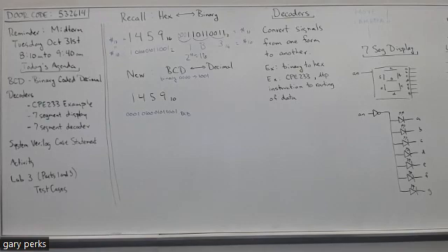And how does a MUX work again? Switches with one. Right. There's multiple inputs. Like if you look at each of the MUXes, the ALU has 2 inputs. And then the MUX that's got the select ALU source B, that's got 4 inputs. The source A MUX has 2 inputs. The PC source MUX has 6 inputs. The RFWR select MUX has 4 inputs.